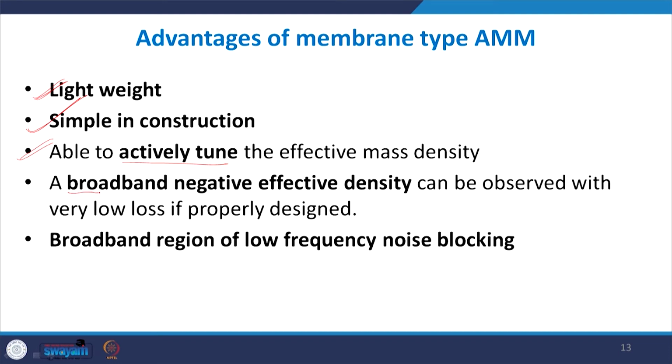And the most important one is that it offers a wide, broadband range where the density becomes negative, and therefore a broadband region of low frequency noise blocking. This is where it is much better than the traditional materials, because traditional materials are unable to perform at low frequencies, and here we have a material that can perform over a broadband range and behaves as a perfect barrier material which does not allow any wave propagation in this low frequency range.